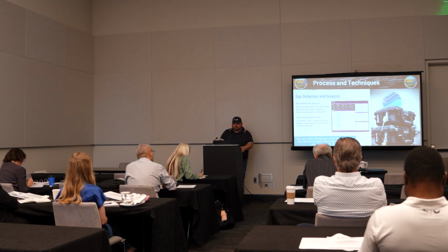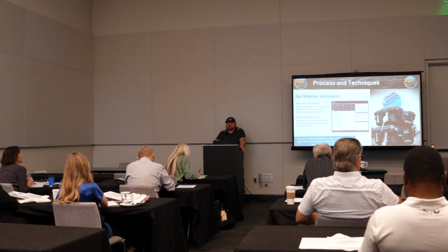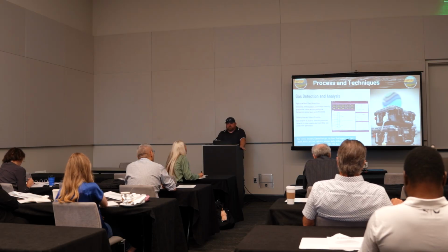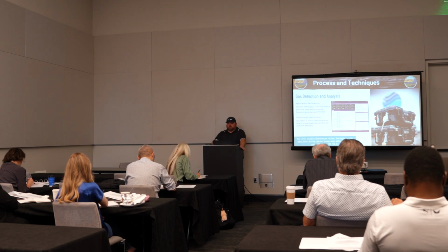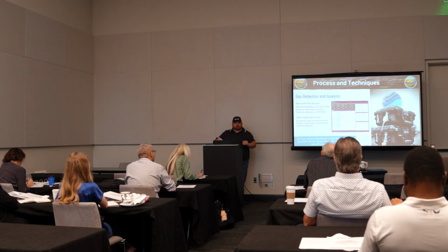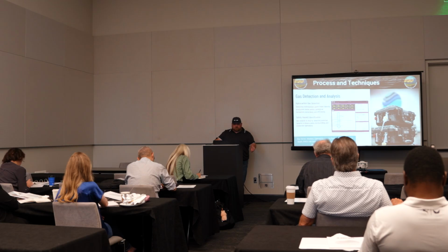On the gas detection and analysis, that's our major part of the analysis, the hydrocarbon analysis. Identifying the productive zones, especially in a vertical wellbore. There are multiple zones those guys are shooting for throughout a vertical; it may be 10 foot thick, it may be 100 foot thick, it may be 1 foot thick.